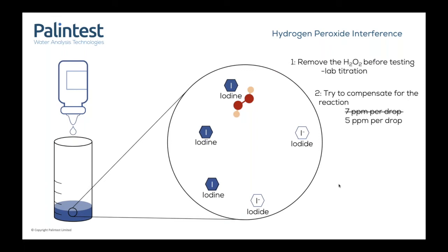In a clean water standard where you take just PAA and just pure water, you can accurately predict how much that's going to happen. The issue occurs when you go to real water, real processed water that is not clean, is full of organics. And what occurs is the peracetic acid and the hydrogen peroxide ratio don't stay the same. In some waters, like fresh produce waters, particularly where you have recirculation, you can build up your hydrogen peroxide to very high levels so that the compensation you've applied isn't really enough and you still get high results.